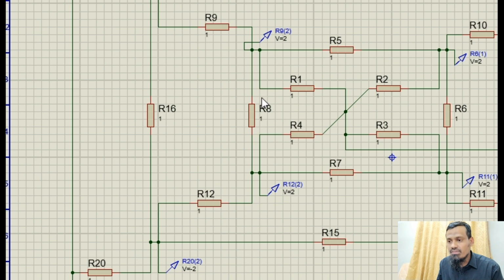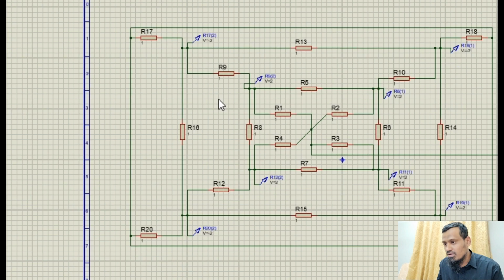As we discussed previously, all these 4 nodes are having equal resistance values and equal current values, so the voltages of these 4 nodes will be equal. Similarly, the voltage of the outer 4 points will also be equal, and that is what I tried to illustrate in this simulation. Also, we will connect an ohm meter across the points A and B, and let us check what resistance we are getting through the simulation.